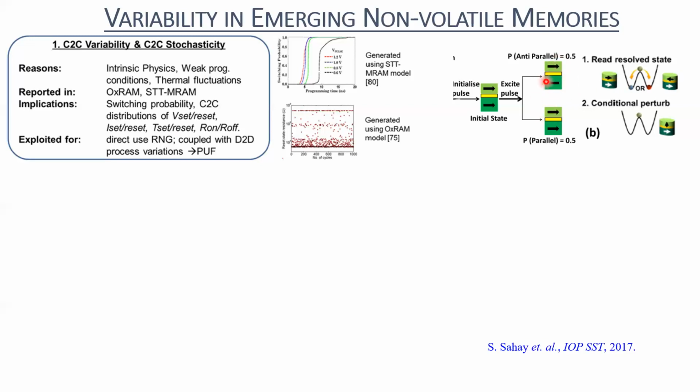However, the problem with STT-MRAMs is that the switching currents required for reorienting, for making this from anti-parallel to parallel state, are huge. The current densities are huge. That is one problem present with STT-MRAM devices. Also, there is the question of how you sense the change in this configuration from parallel to anti-parallel and so on.